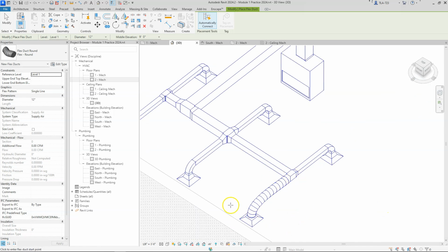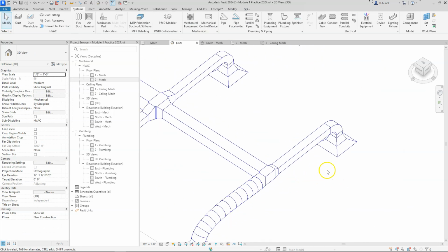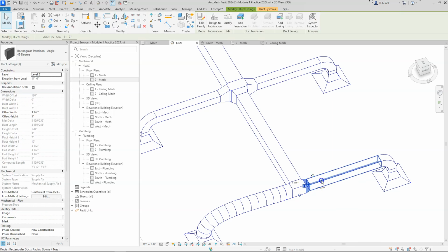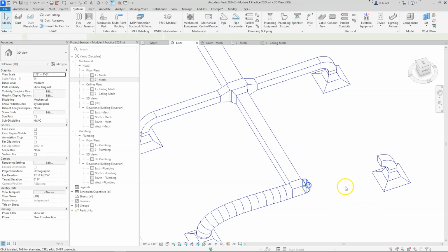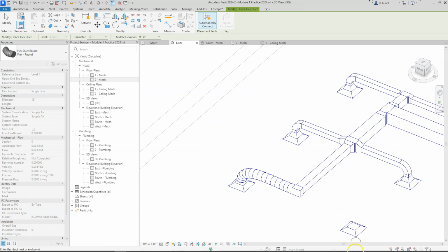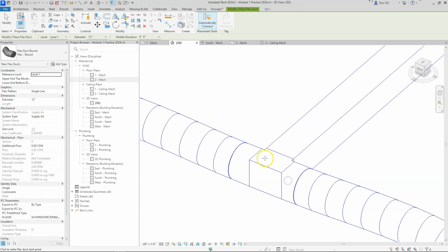Now never mind that that flex duct looks overly large right now. We're going to go back and resize the system again just to get that back to a normal size. I'm going to go ahead and just do this side also. So we'll delete this and this all the way down to the diffuser again, and we'll just repeat that process. Flex duct from here. Sometimes it's helpful to spin this thing around so you can see the face that you're trying to tie into, and click.